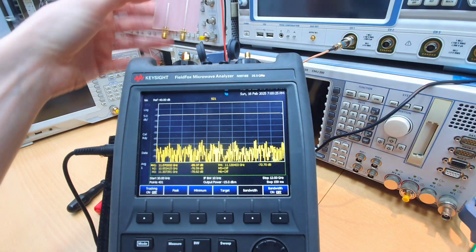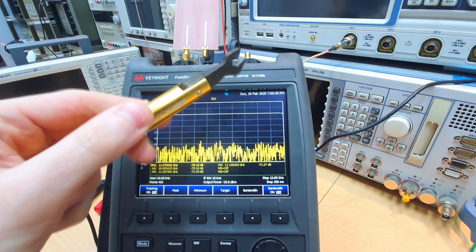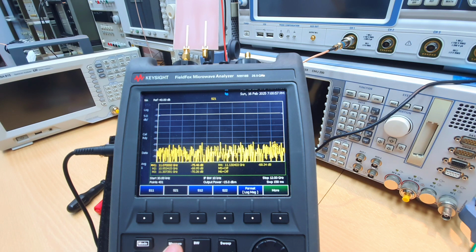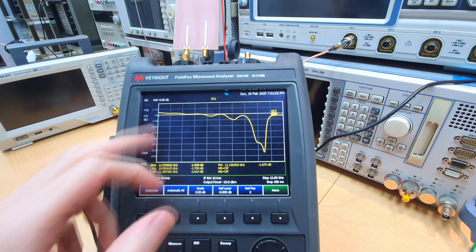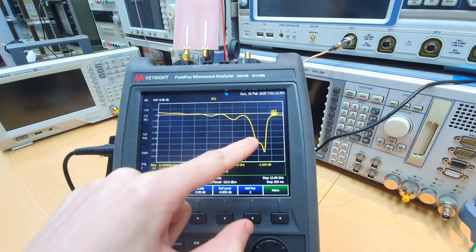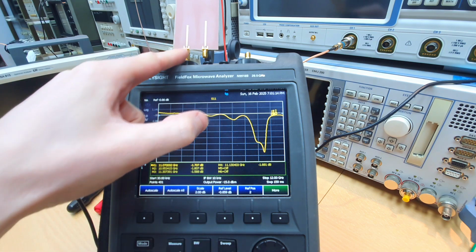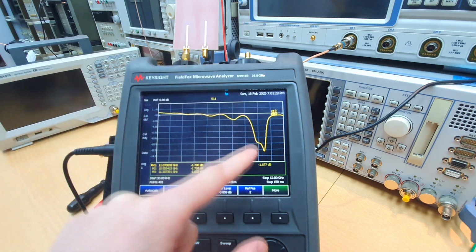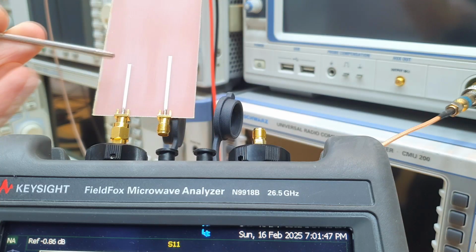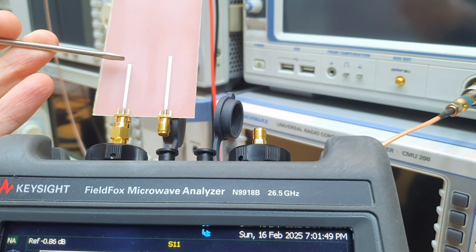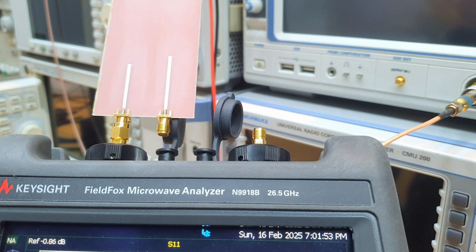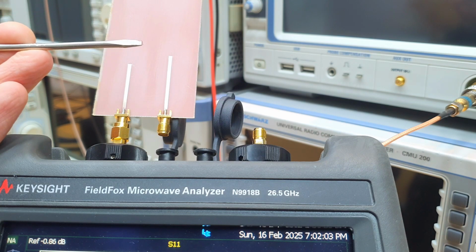So let's connect it here. Of course, for the real measurements I used an SMA wrench, and we are going to measure S11. And of course, guys, it is 0 dB, right? Up to this resonance that is actually the microstrip radiating. That line makes a very good antenna at 10 gigahertz. Interesting. All the energy is reflected back because we have an open termination here and we see a 0 dB trace for S11. You can read that as 100% reflection.